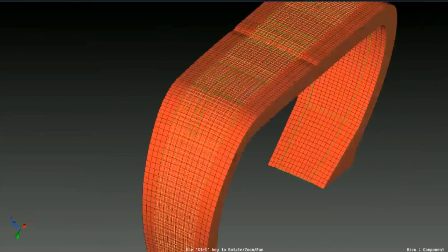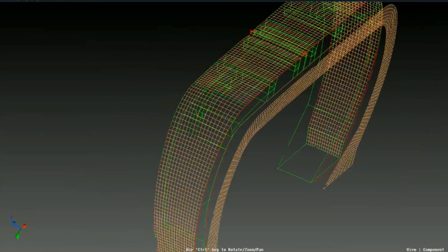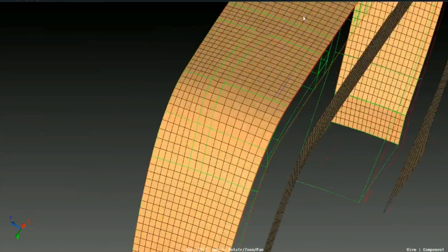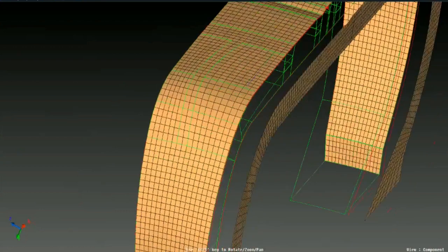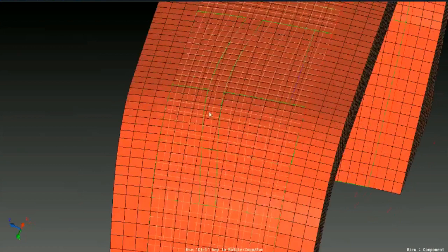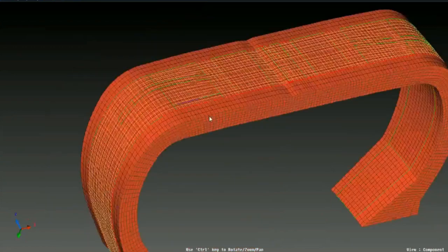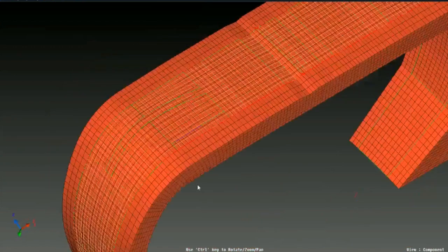So now here I'll just turn off my 3D and turn on my 2D. Now I can see how nicely our 2D mesh has been created with all the features captured. And if I look at my 3D mesh, it is not aligned with the features, as we can see here. So to align it, we have an option that is imprint top mesh, where it will go ahead and imprint or propagate the top mesh onto the hex mesh so as to get our final output.